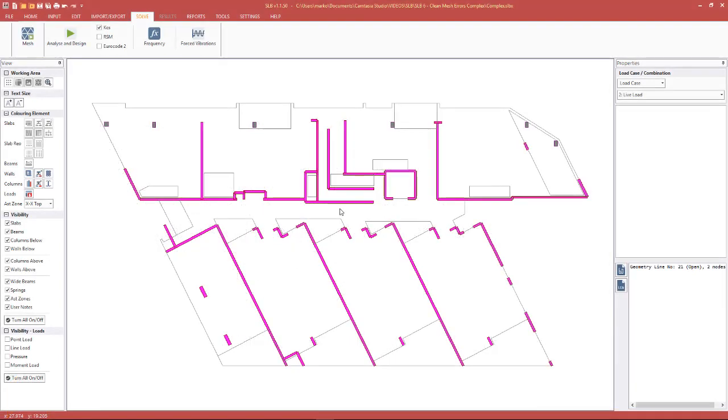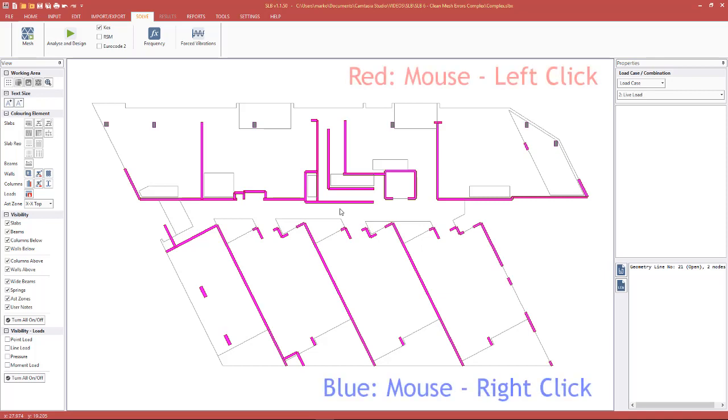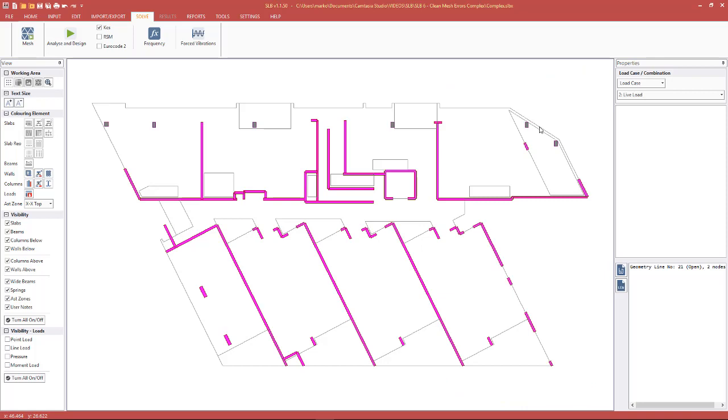Looking at the floor, we can see that a vast portion of the geometry is in the diagonal. So just this entire half, and a lot of the slab edges are also in the diagonal. These types of models are very sensitive to meshing errors and are also very sensitive to analysis errors. Especially in RCB, these models, unless they're cleaned up, can cause a lot of headaches. Basically the analysis can fail. Obviously, cleaning up models such as this in RCB we'll go into that in more detail in other videos.